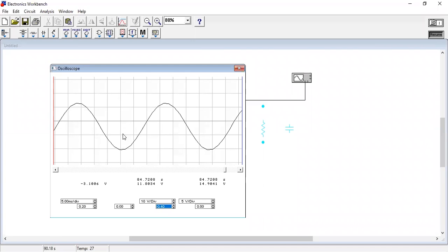And we have to find the time value, the difference between peak to peak. To find it, we can change the x position and measure the difference between two peaks. You can see one division belongs to 5 milliseconds, so one box is 5 milliseconds. There are 6 boxes and 5 parts.